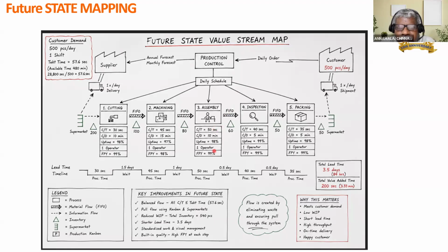So that's why you are collecting the data, right? So suppose now you are identifying this as the choke point. So there already you have the time, right? Say for example, everywhere else cycle time is 1 minute. So here it is 3 minutes. So that means the process time is the issue, right? So as I was telling you, if it is more only by 20-30%, try to see whether you can improve the efficiency here. But suppose here you are taking 1 minute, here you are taking 3 minutes, then with 3 times maybe you may not be able to improve the productivity.